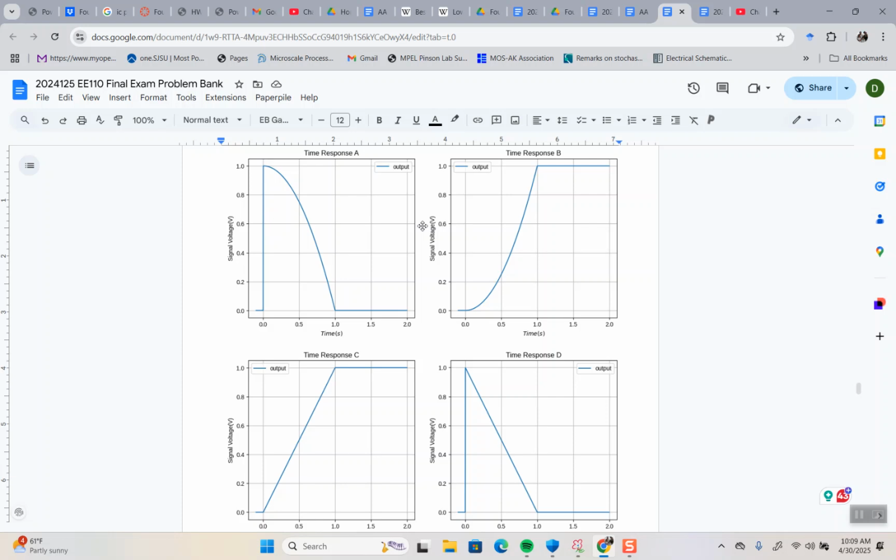So this is high at the beginning, like an edge, right? A step function has an edge. That edge is passed through and it goes down to 0. So this one is high pass, right? This one starts low and is passing this DC signal. So it's not a shape we're used to, but it's a low pass.